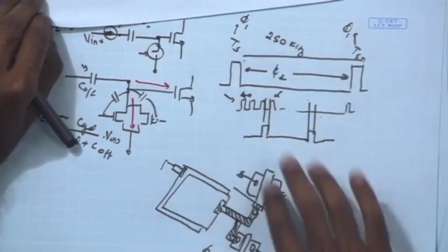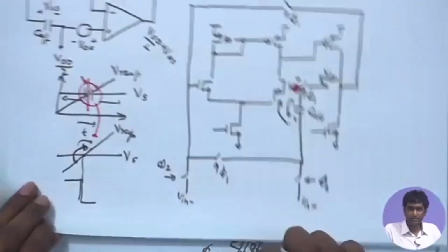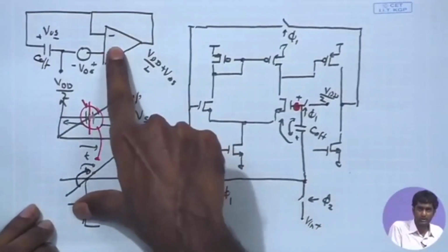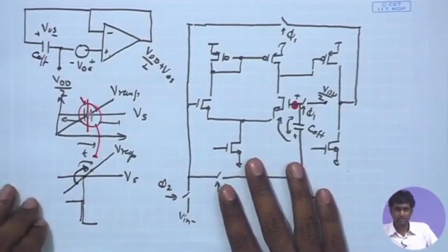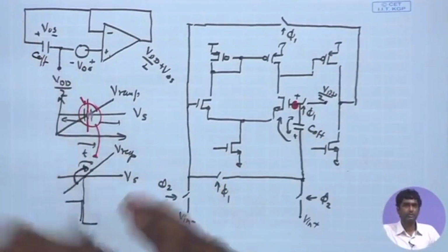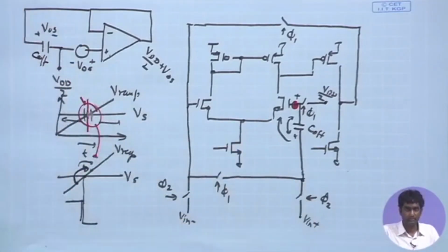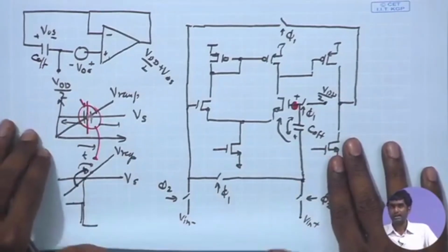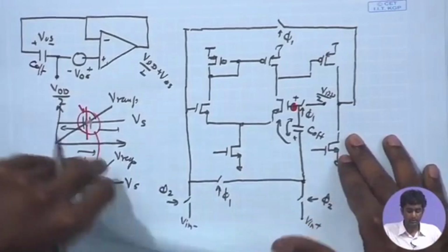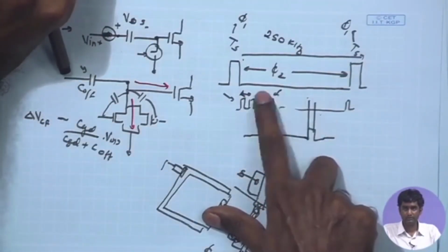Or is the impact less serious? Can it be tackled in some other way? So, can we afford a slower comparator? In our design example, the comparator speed is not so critical because we are still dealing with 7-bit resolution, but if you go for larger and larger resolution, where 8-bit, 10-bit, 12-bit come in, then we can imagine what the requirement of the speed for the comparator is going to be. And in that case, can we afford to keep our comparator slower than the clock pulse? You can think about it, we can discuss this point later.